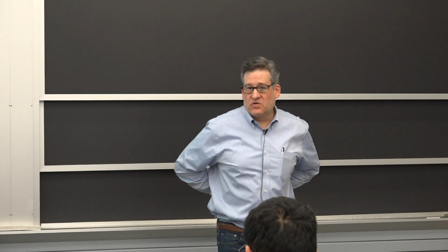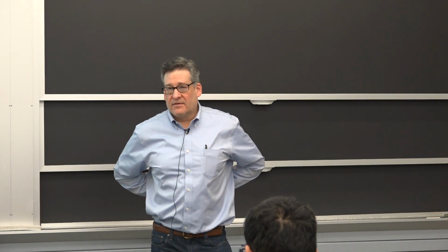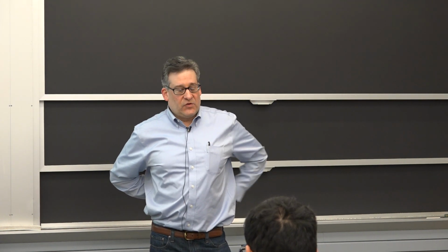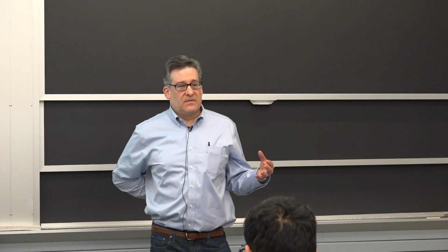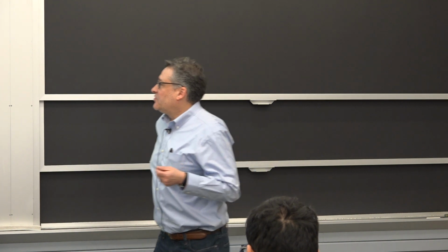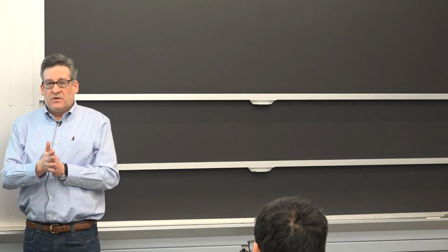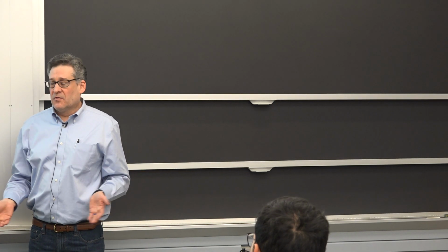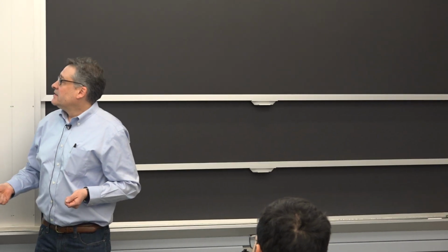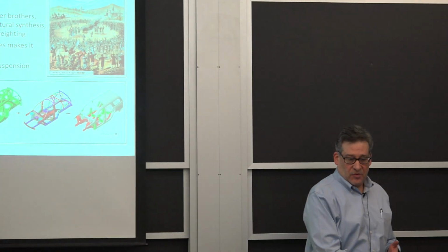Topology optimization is a tool that we're going to focus on. We're going to talk about it a lot. This is a tool for optimizing load paths. The two examples you see here are topology optimization. This is a suspension component for a car. This is something I worked on when I was at Chrysler. This is a tool we used. We used topology optimization to reduce the weight of an SUV structure. And then we'll talk about a bunch of other tools.